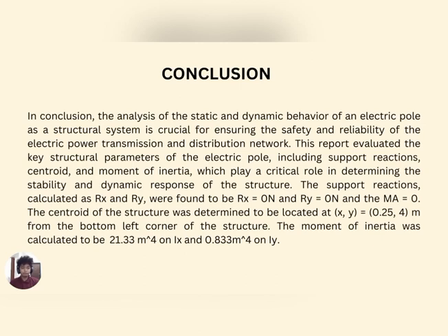The centroid of the structure was determined to be located at x and y, which is 0.25 and 4 meters from the bottom left corner of the structure. The moment of inertia was calculated to be 21.33 meter power of 4 for inertia at x and 0.833 meter power of 4 for inertia at y.